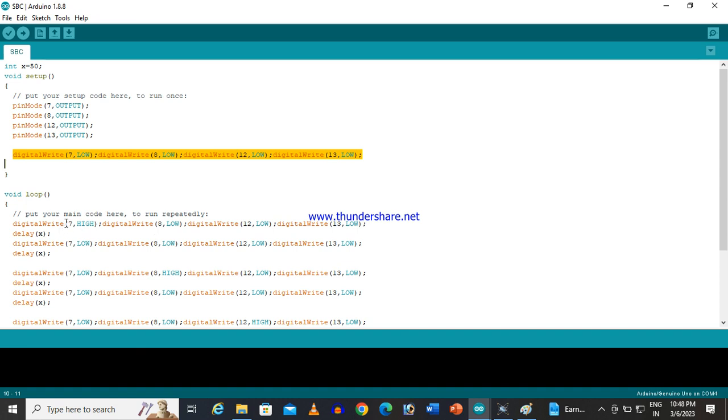Then I make the first selection bit high and hold it for a time at least equal to the conversion time of the ADC. Then I make all the selection bits 0 again, giving a safe pause so that the switch is completely off.